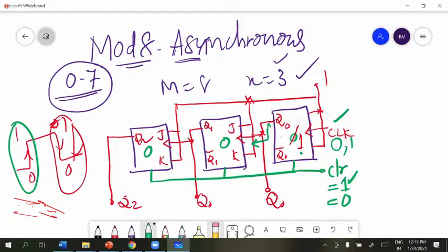So when the clock is here, this 0 is applied here. Nothing is changed here. Whenever you give the first clock pulse, the first flip-flop output is toggling, and instead of 0, you are getting 1 here. 0 has become 1. You just remember this. This is a positive change. Because of that positive change, this is not changing. So the entire functioning of the flip-flops is based on the clock signal.